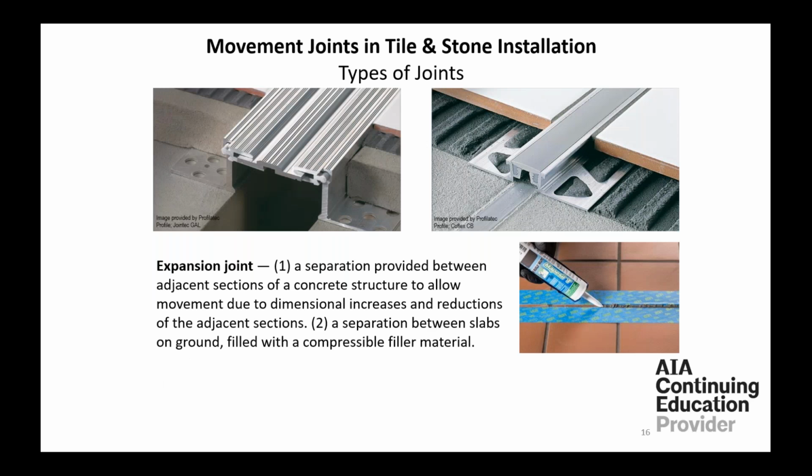All right, a few pictures of expansion joints. So there's a variety of ways of doing it. One picture we don't show here, and we will get into more detail a little bit, is walls. You also have to have them on walls for that matter. There must not be any reinforcement across the joint. It's an actual separation in the structure. And so in turn, we need to continue that through the finished materials.